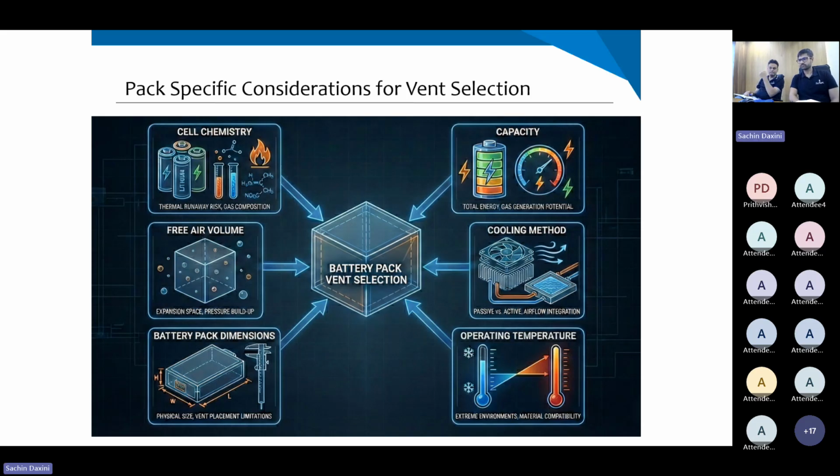Next question from Yash is, does water or dew present over the membrane affect the airflow during the venting? No. Even if there's a very high amount of water or moisture, water droplets on the vent or the membrane itself, the membrane being super hydrophobic, the breathing characteristics will remain practically the same. So there is a negligible difference, if at all.